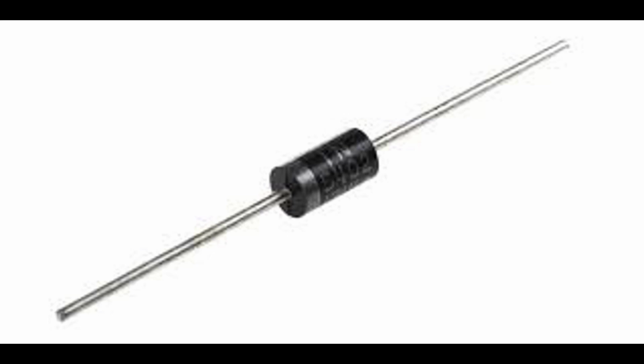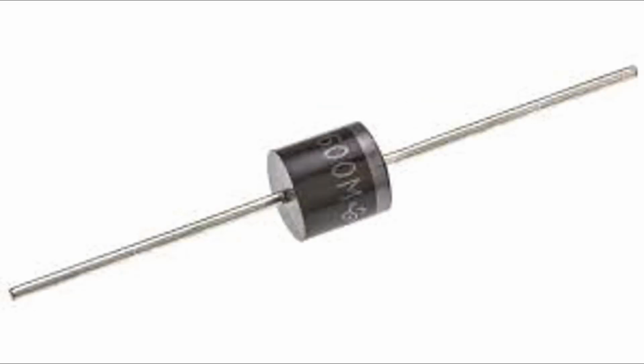Below this threshold voltage, the diode remains in the off state, blocking the current. Clipping action: as the signal voltage increases beyond the threshold, the diode effectively clips the waveform by limiting the amplitude of the signal. The portion of the signal above the diode's threshold is removed, resulting in a distorted output signal.